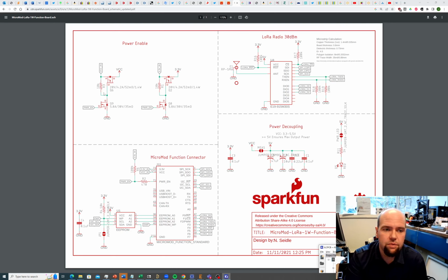You have to use a pull-up resistor to get the high voltage on the gate. And you have to use an NMOS to pull that down. So you have to use a pull-up resistor if you have a low voltage switching on and off a high voltage. But this is a good way to do it. And I'm going to do it for this one.